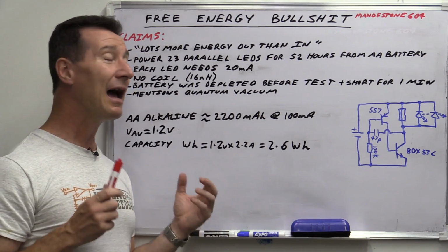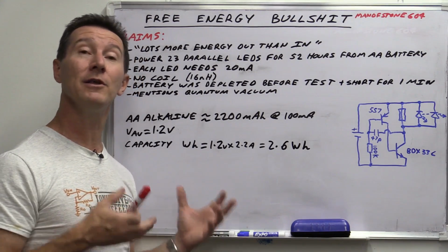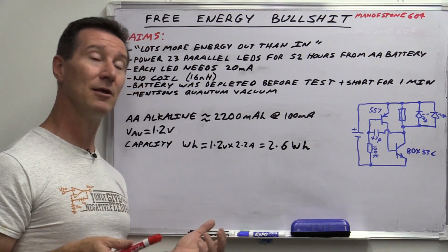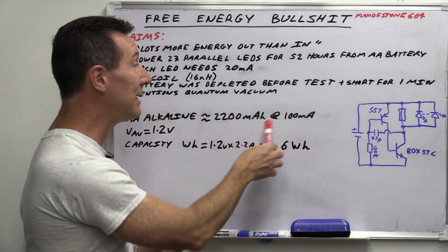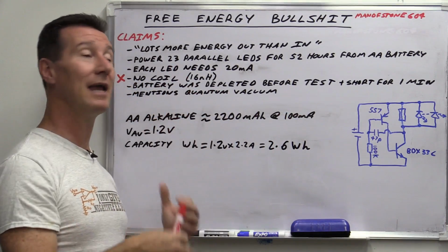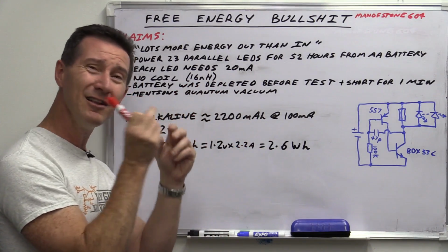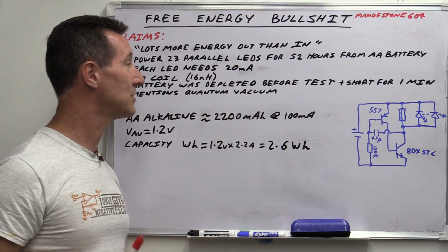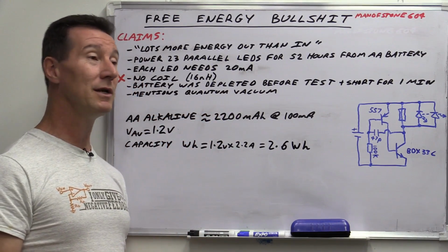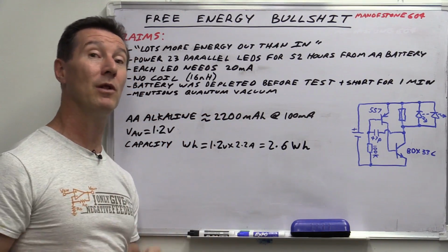And somewhat contrary to popular belief, the no-name kind of alkaline batteries you get out there aren't that far off the really good Energizer. In fact, in some cases they can meet or even exceed them. Depending on what the discharge current actually is, because the characteristics change, there's little variations in the battery chemistry, all that sort of stuff. Anyway, for the ballpark engineering calculations we're doing here, we're going to say they're pretty darn well equivalent.